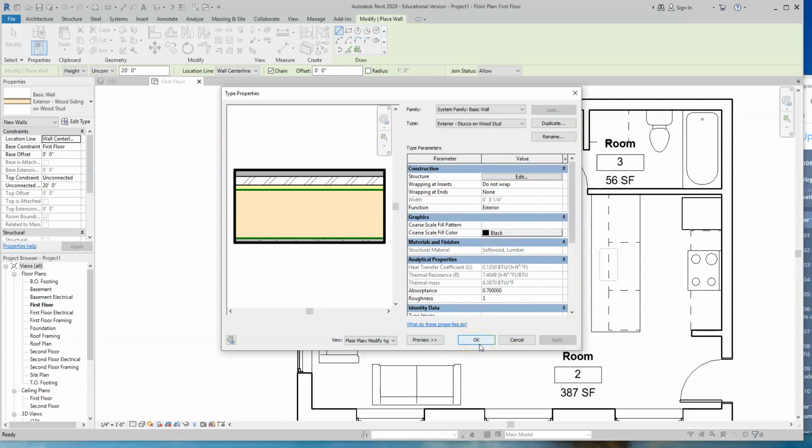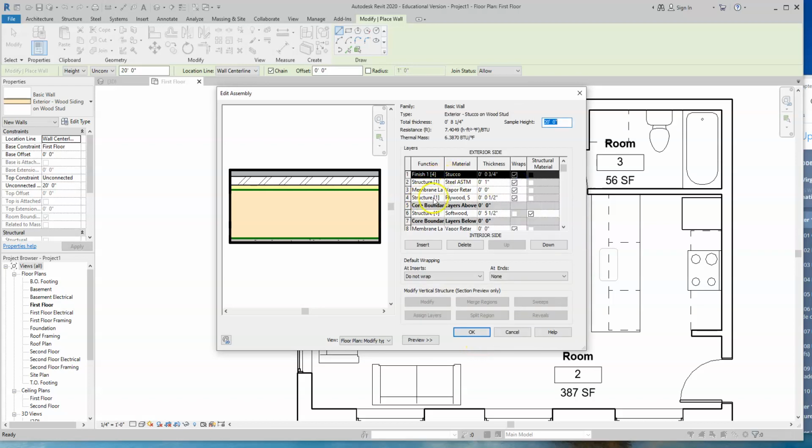So I just made that little last change. On the 4th line, it was saying there was a problem, maybe because it stayed as the core boundary, but I made sure the plywood said it was under structure, and after changing that, everything looks fine. This one's probably supposed to be a finish, but we'll just leave it there since it did accept it.